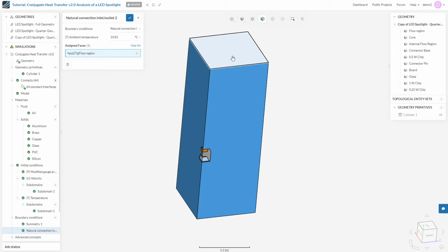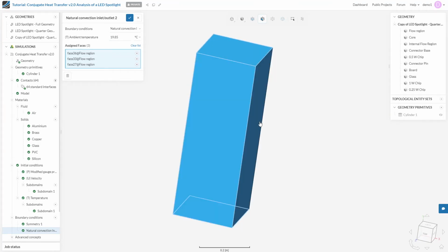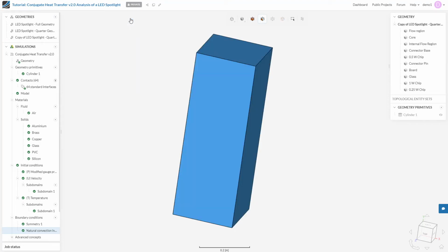All the components of the velocity tangential to this face are 0. For the temperature, it takes the form of inlet-outlet in OpenFOAM terminology, which means that the outlet values for temperatures will always be zero gradient, while at the inlet, the temperature will be regarded as fixed value, and that fixed value needs to be specified here. I hope that makes sense. So let's assign the remaining faces, which will involve the already assigned top face, bottom face, and the remaining side faces. You can also change the name of the boundary condition just to make it more representative. Save. We are done with boundary conditions.